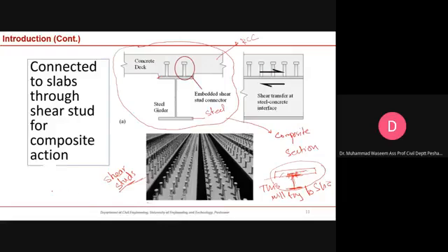For example, you want to connect your foundation footing. Like you did some footing, this is the pad of this footing, and you realize that the depth of this footing is not appropriate. It cannot resist the demand. What you do, you want to do more concreting on that to enhance it, but the connection is not there. What you are going to do is insert some studs, and in this way these two concretes become a single section, up to some extent. Shear studs, or studs you can say.